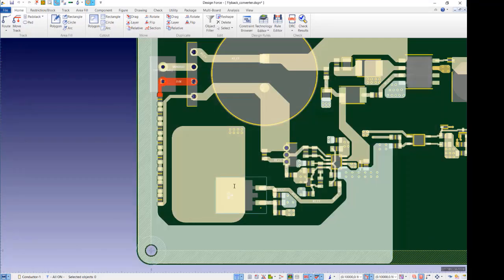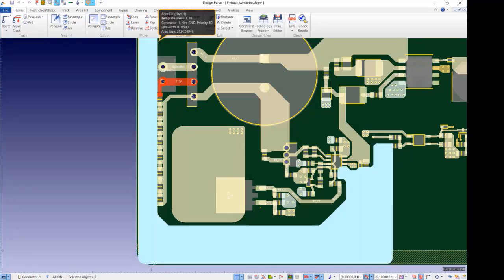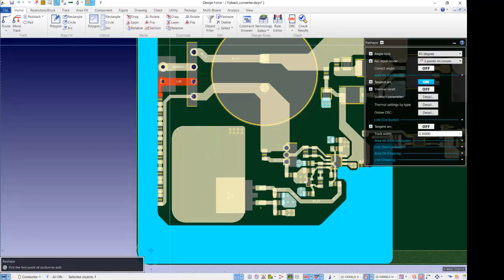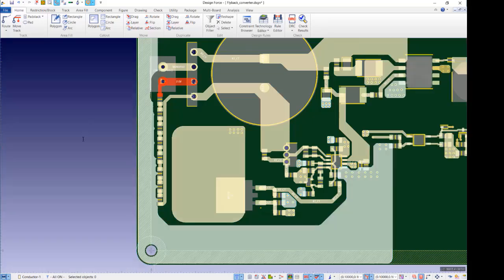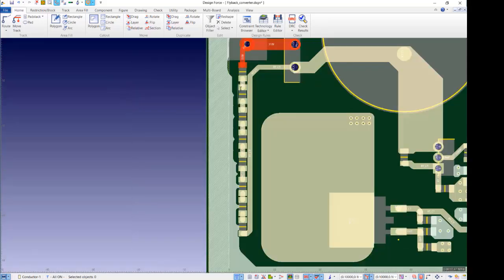And then I just want to make some edits onto my copper plane here just to show you. So if I was to say reshape, just select 2 points, data end. Now you can see those rules have been applied, and you can see as an example where the voltage gets smaller down this potential divider, so the gap is getting smaller as well.